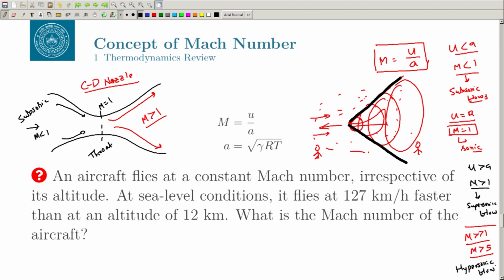And one last situation is when the Mach number is between 0.8 and 1.2, somewhere in this region. This is called transonic flow. Why is it called transonic flow? The Mach number I am talking about is the free stream Mach number, but you can also have the local Mach number, where you take the local velocity and local speed of sound.